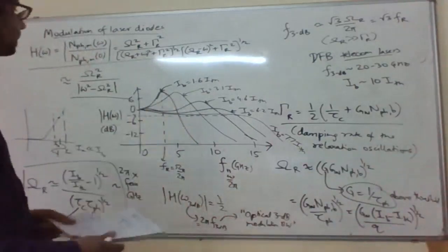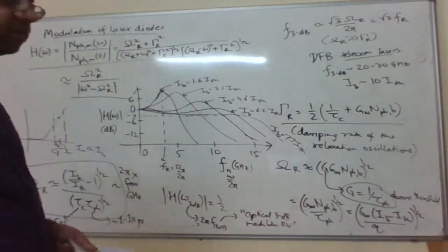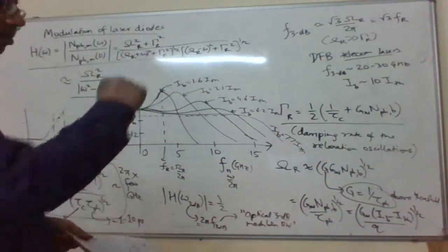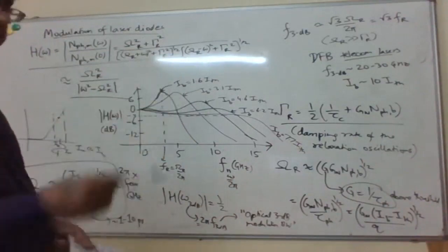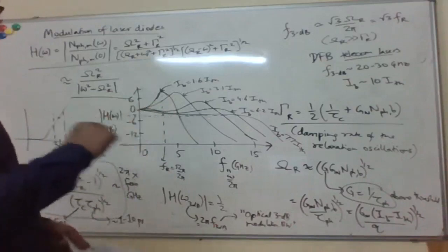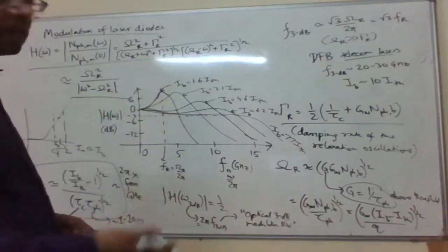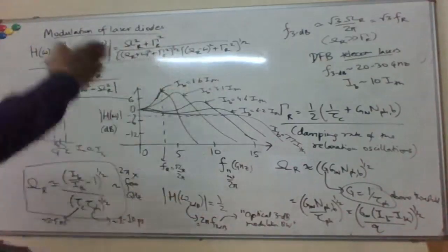So basically you want to send a pulse. In the simplest scheme of modulation, we want to send a pulse having some high power for bit 1, and then turn the laser off and send no power or very low power for bit 0, right? That is what is known as large signal modulation or digital modulation, where you are turning the laser on and off.